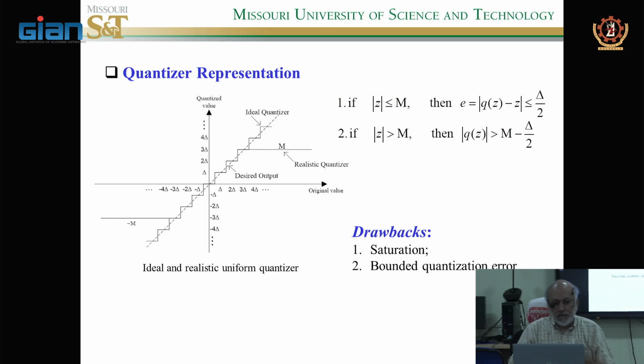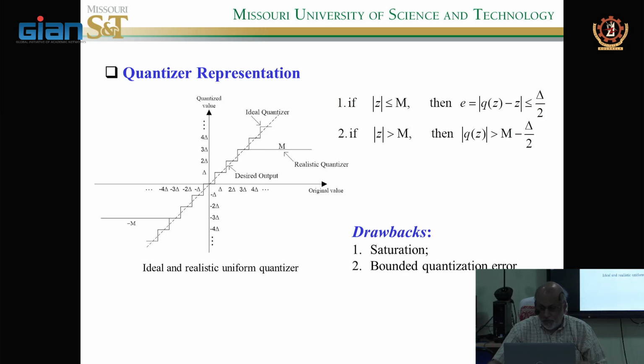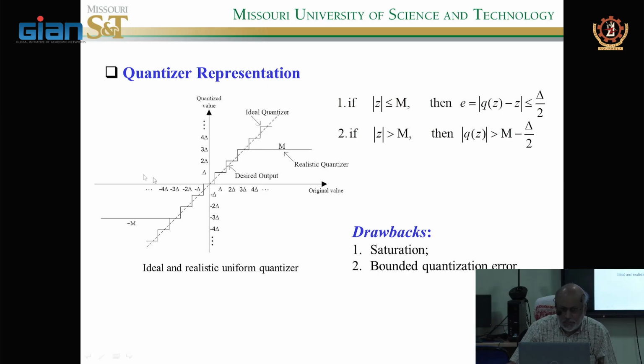Alright, so here is the quantized stuff. You can see the original value, and here is the quantized value on the y-axis. Now you see the dotted line, a straight line. That is the ideal quantizer, the mathematics. Basically, that's a linear line which says that based on the current value, you get a quantized value. So there's no loss. You understand that in the linear line? That's what mathematics does. But in hardware, you see that there's a step function. That's where the hardware does it.